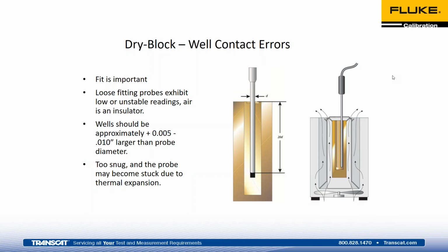All right, so fit is very important. As we talked about the dry wells having either fixed blocks or inserts, you notice that there was a lot of different sizing options, and fit is very important. Having a sensor in a well that's too big typically results in some sort of insulation or a low reading.